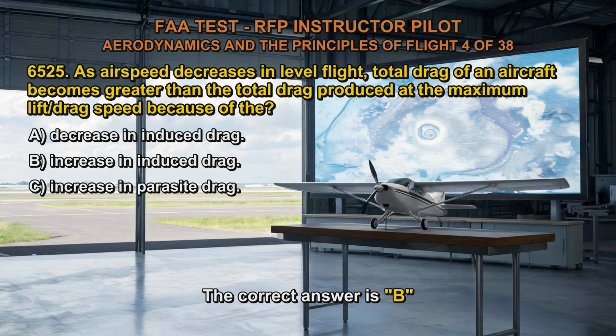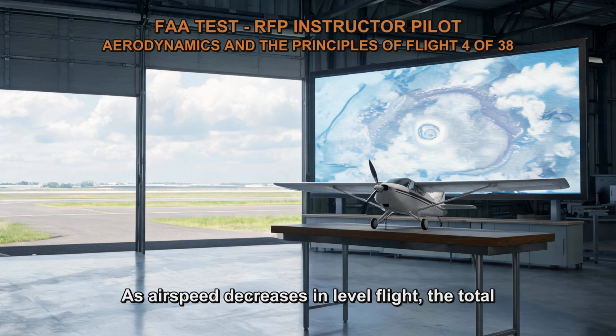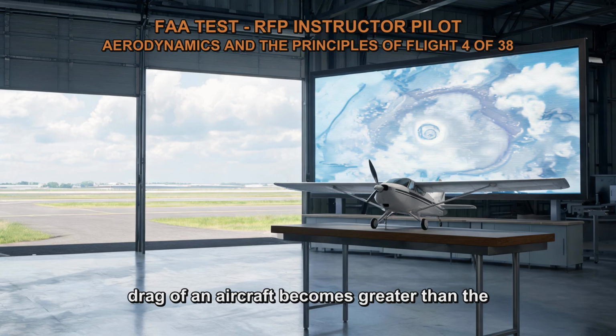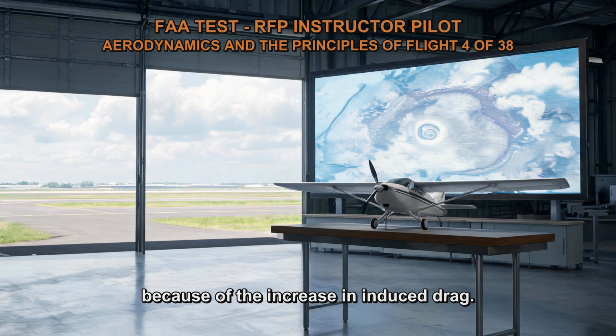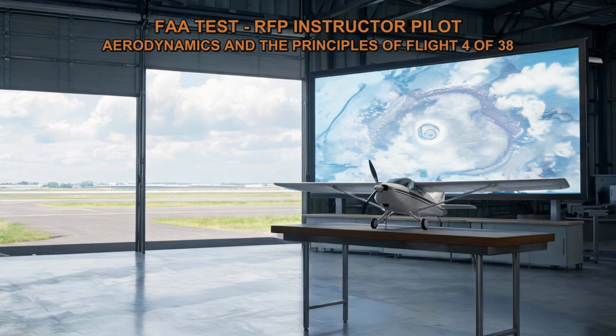The correct answer is B. As airspeed decreases in level flight, the total drag of an aircraft becomes greater than the total drag produced at the maximum lift/drag speed because of the increase in induced drag. Induced drag is a type of drag that is generated as a result of the production of lift by the wings. It is directly related to the angle of attack and the lift being generated.